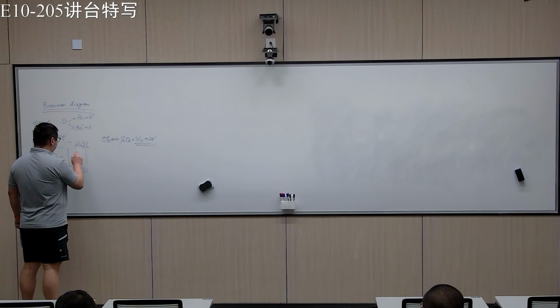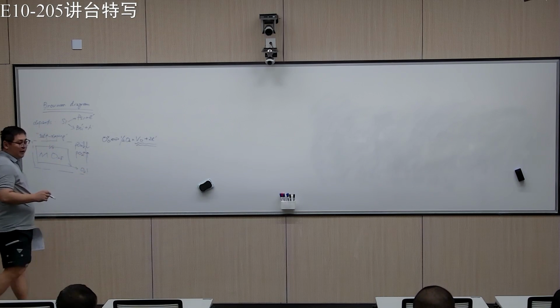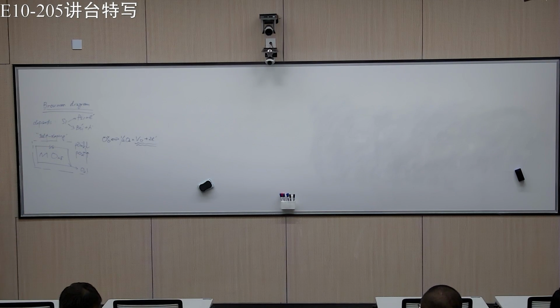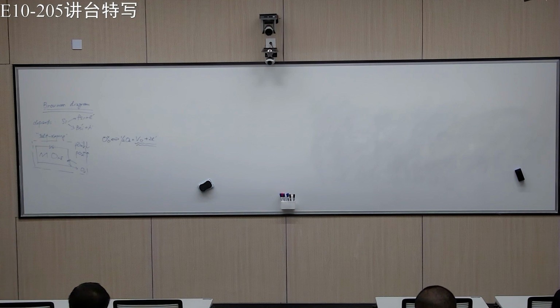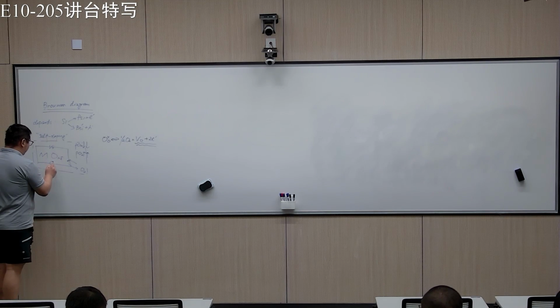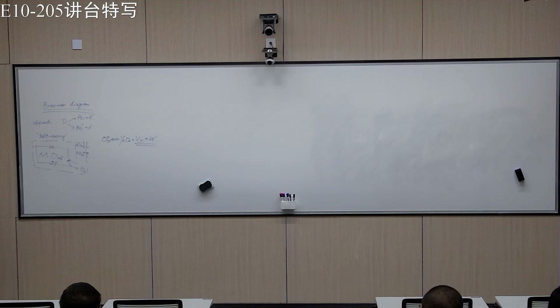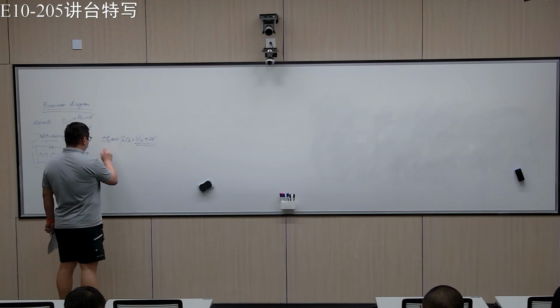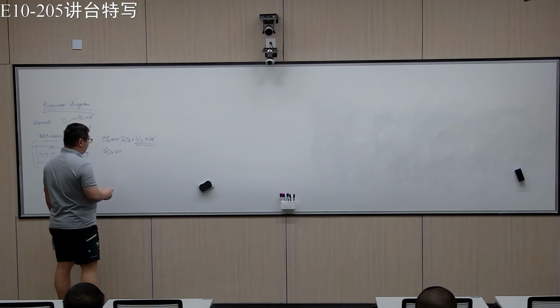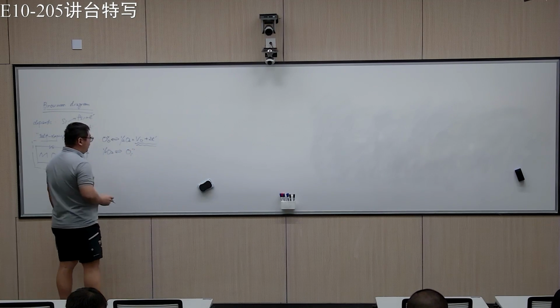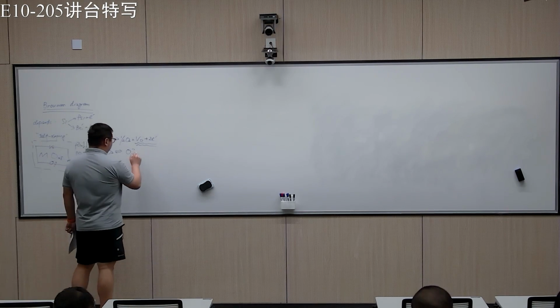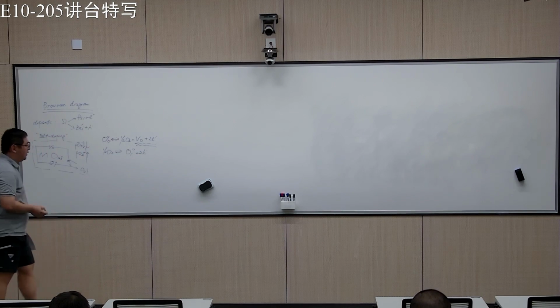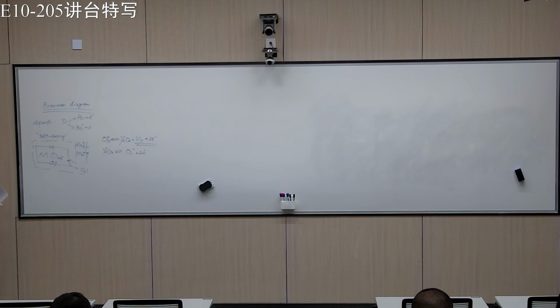Okay, now let's say PO2 is very high. So we increase, or pressurize, the PO2. Then oxygen will go into the sample, right? So let's say it creates oxygen interstitials. Now it's MO 1 plus delta. The oxygen goes into the sample and becomes oxygen interstitials, and because oxygen is negatively charged, you have to balance the system with holes. Now it's equivalent to this p-type case here.